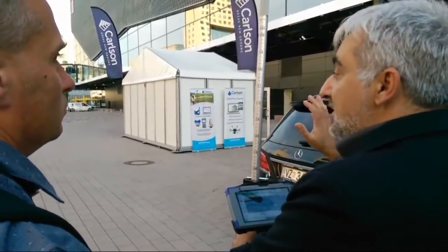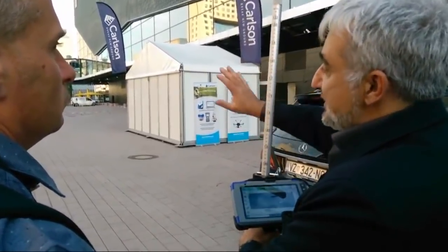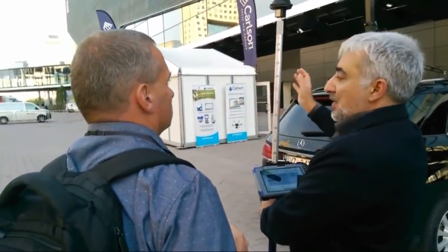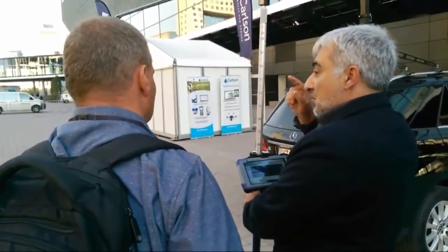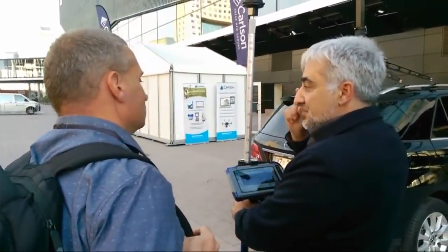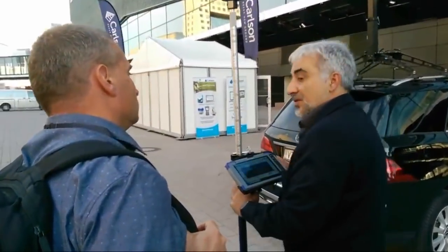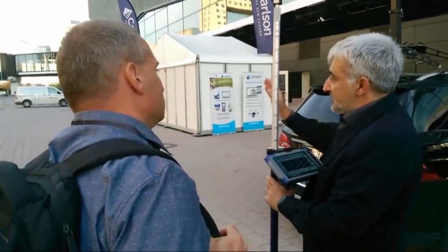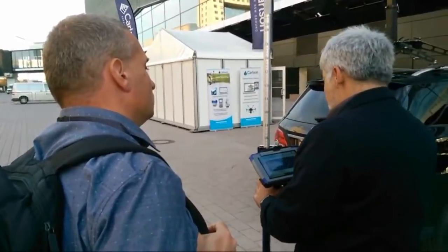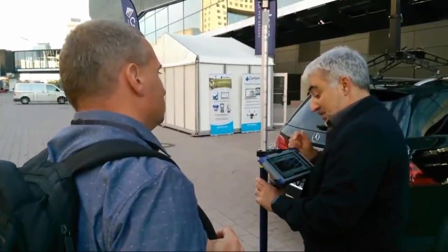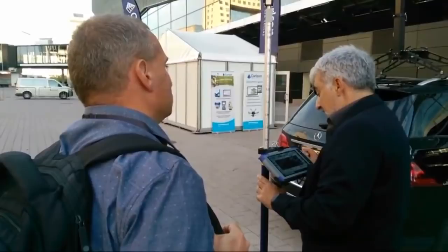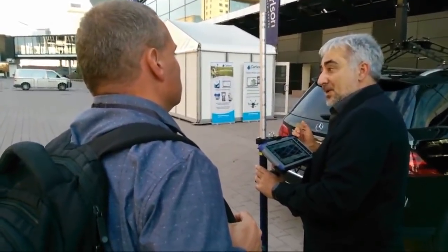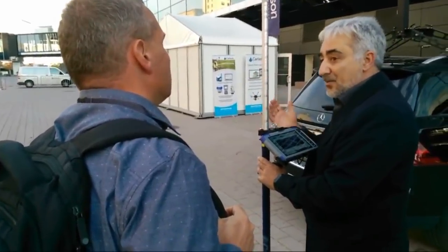And when I get into the distance meter area, let's call it, if the field of view of the distance meter is like 1 or 2 degrees, then we command the instrument to start searching, even if it didn't start searching because you are in view. So you can search and find the prism so that when you are getting close to the point with the GPS first, then you get locked. And when you are refining the position of the point, you already are in robotic mode, automatic.